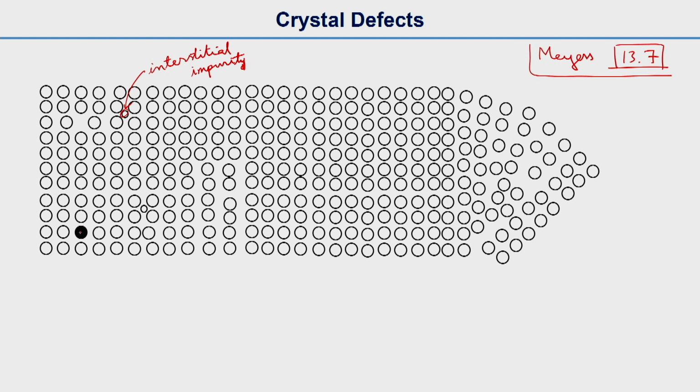Interstitial sites are in between the regular lattice sites, and this other one is again an impurity, called substitutional, which means that the atom is different. Let's say all the other atoms are aluminum, and one atom is a copper atom, so that's why it is called a substitutional impurity. There can be a high number of impurities, but we are showing only one of each. And then this is an extra half plane, which is the dislocation. Actually the dislocation is the line perpendicular to the plane of this slide. This is actually an edge dislocation.